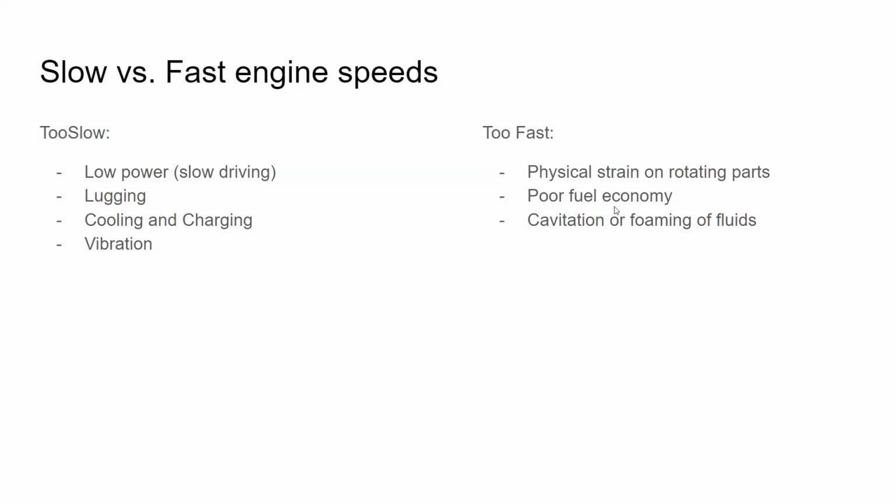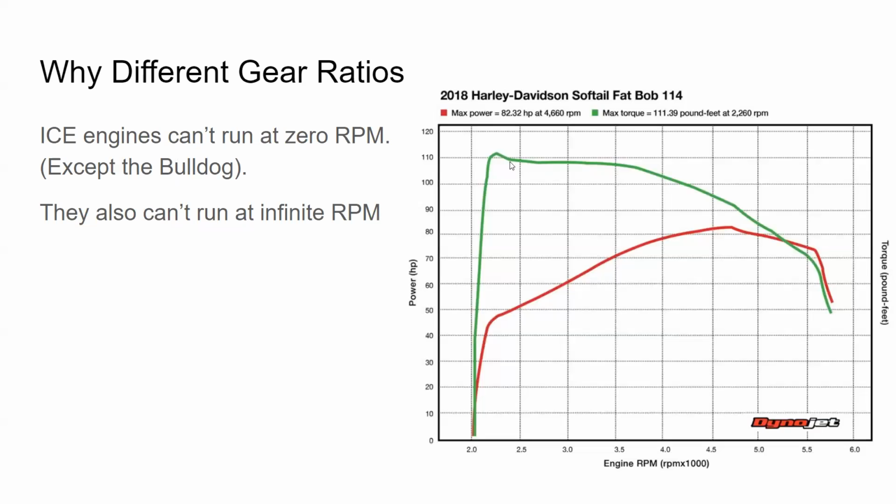There's a sweet spot where piston speed relates to good fuel economy, and outside of that, you're not burning fuel effectively, and that's why graphs like this have this high point right here. This is where this engine is really good at turning fuel and air into kinetic motion. And then beyond that, maybe it doesn't have enough time to burn all the fuel and a lot of it is being burnt in the exhaust system or something, but it's becoming less and less efficient at turning fuel into kinetic motion down here.